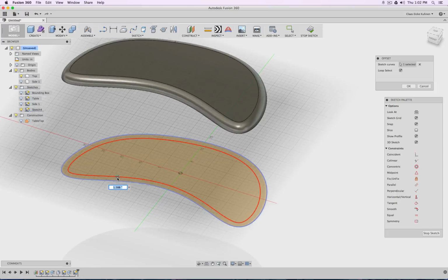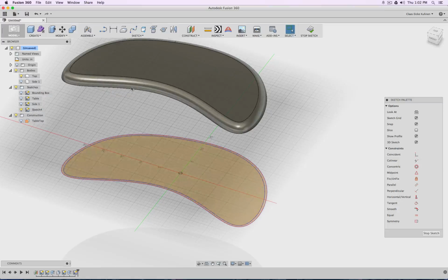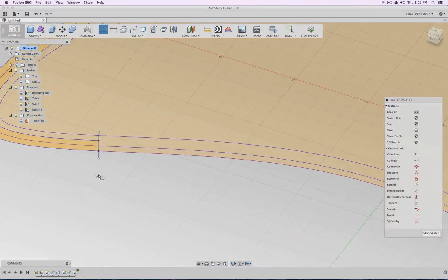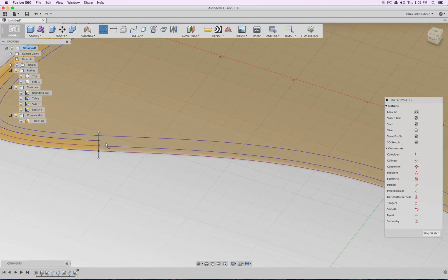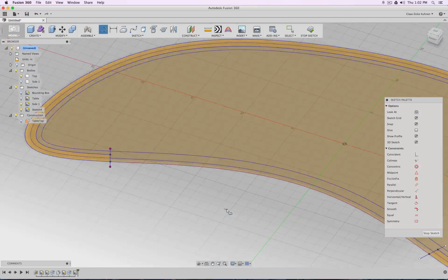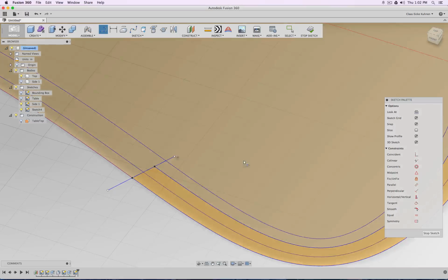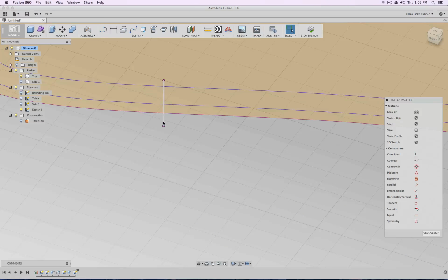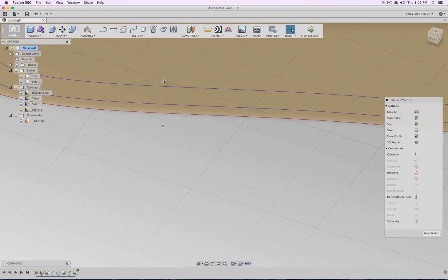So the first offset maybe 0.5 inwards, and then I make another offset 1 to the inside, and for example that should be at the same position of these lines. So click. See, I clicked on the endpoints of my original line here. I could even simply project this line in there, and this I delete, this I delete, and say project this one in.